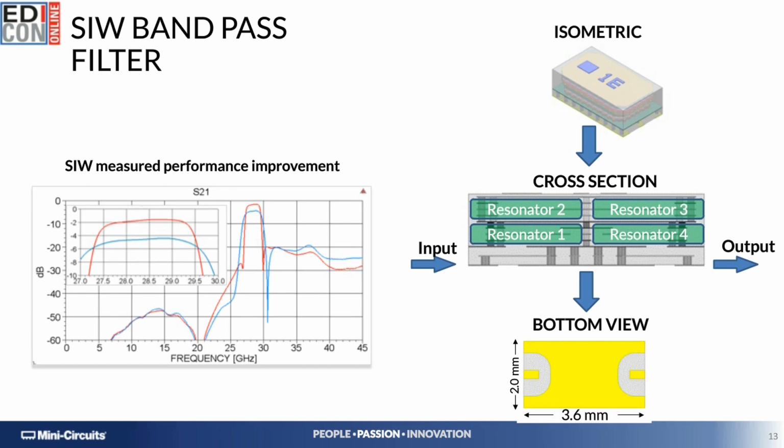advanced technological materials which are composed of improved powders on the LTCC side, as well as conductive pastes on the conductor side. We're looking here at a substrate integrated waveguide centered at 28.5 gigahertz with a 7.3% bandwidth, with an impressive mid-band insertion loss below 1.5 dB. These substrate integrated waveguide topologies are enabling very narrow band bandpass filter implementations with low losses up to the millimeter waves.